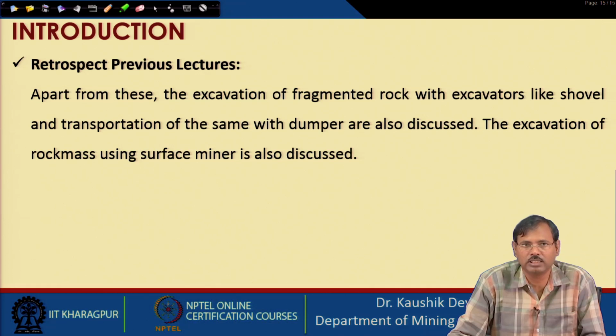So, this is in a nutshell how the dragline works, which we understood from the videos and photographs in the last class. One very important point is that the bucket is always under the hoisting through the hoisting rope, and that is why there is no strong contact between the boom and the bucket.